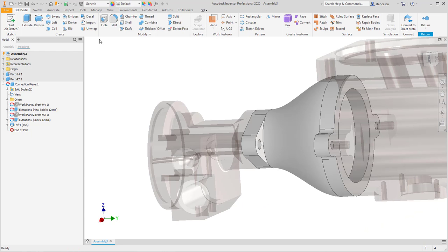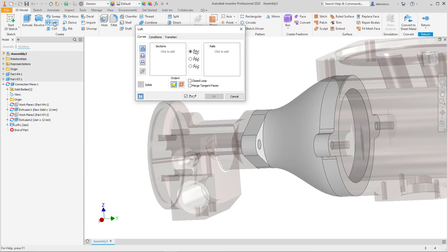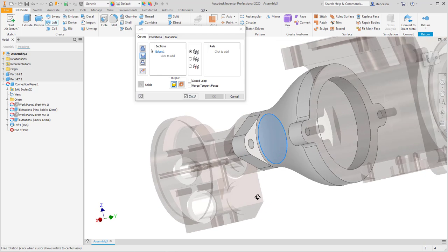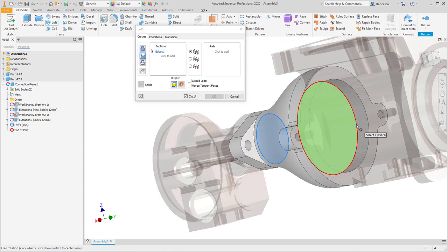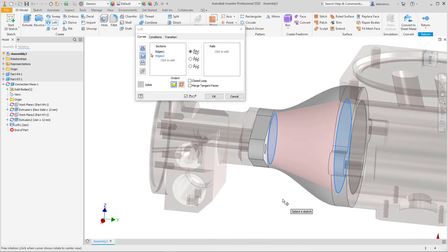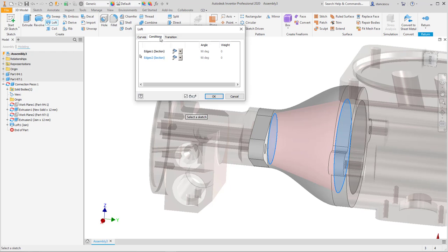Okay, I have to create another loft, but cutting this last feature, choosing the interior circle, real one. This is a real circle here, I don't need a sketch, and this one also real, to connect the features, and again choosing this tangent and this tangency.